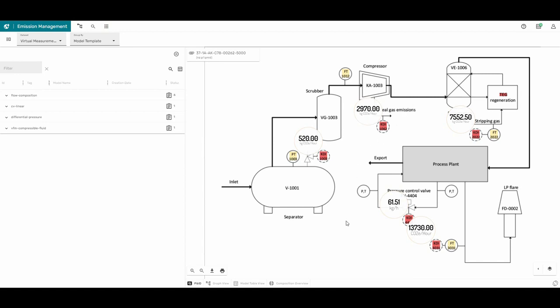We also have a pretty strong library of physics-based models that, for example, based on a pressure control valve with upstream and downstream conditions, could estimate the flow through parts of the system where you don't have a flow transmitter, and link that back to potential emission sources, more indirectly, like this tank example or a separator example, where it could have a venting type of emission or other relevant factors that you want to track over time to see if you can improve, or at least be aware that you have an emission source that is hard to measure with the more classical approaches to emission management.